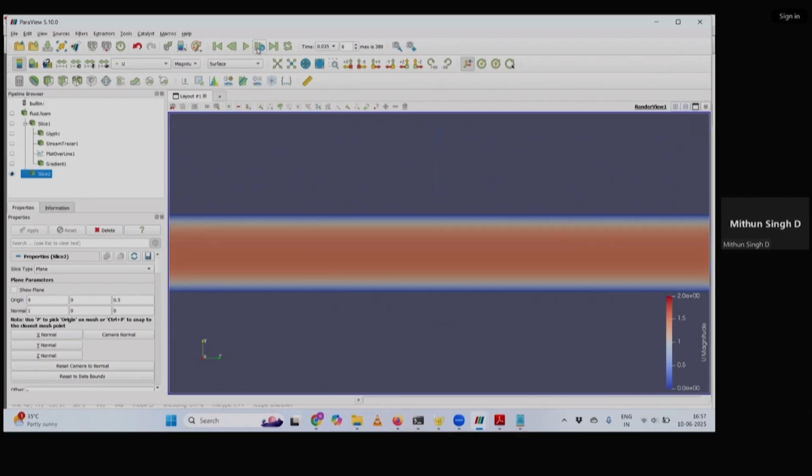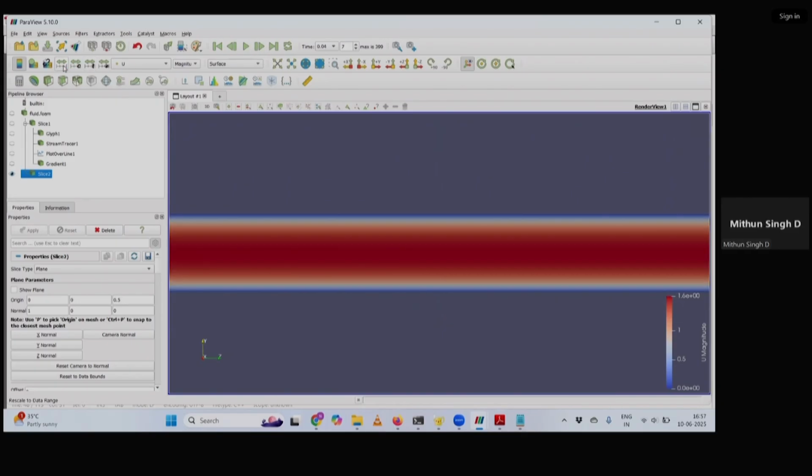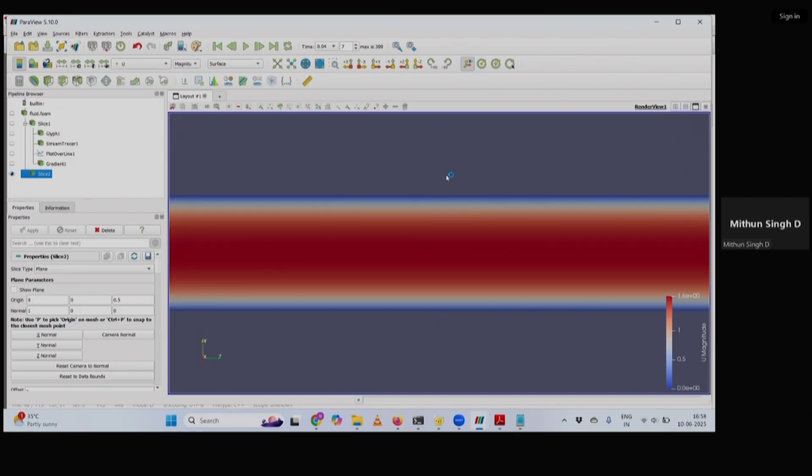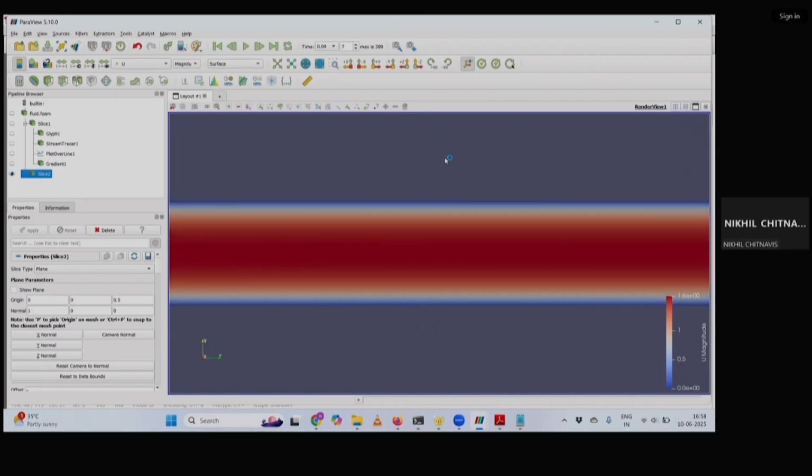But what I'm trying to ask is, we plotted the graph at that time, right? Not the plot, but similar to the plot, can we bring it in the visualization, as a contour itself? Okay, that you can also do. Like an ISO surface maybe? Yes, something like that. But ISO surface can only be plotted using a scalar quantity. So instead of a scalar quantity ISO surface, you can plot it something like this also.